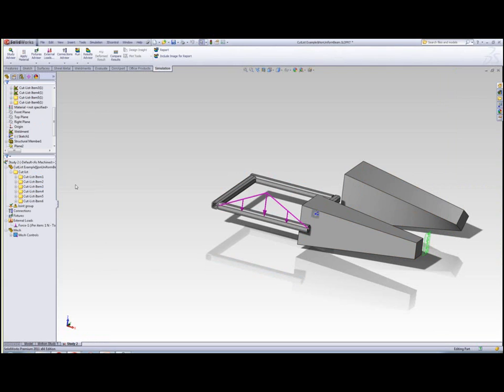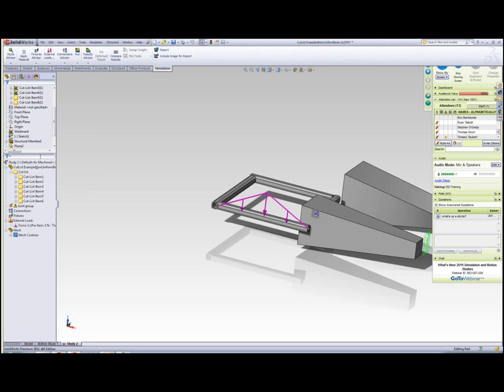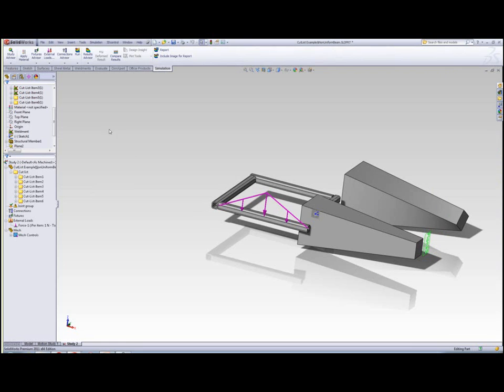What's nice is you can drag existing pressure loads to a subfolder under the external loads folder, or any other attribute. This way you can mass select and set up your studies a little bit quicker. Something else that's new with the simulation is this little filter here. This works just like it does inside of SOLIDWORKS. We have the filter, and now we also have it in simulation.